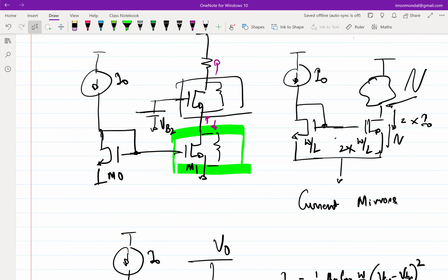Okay, so why do you say that? Also, we have a GDS. His question is, is the current through this I0 the same that is going into M0 or not? Where else will the current go? M0, but also not a GDS 0. Correct, we have a GDS 0, right? In the incremental domain, we have a GDS. Yes, agreed.